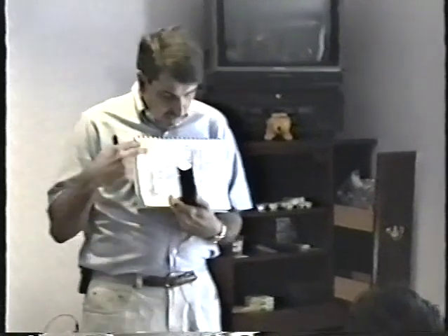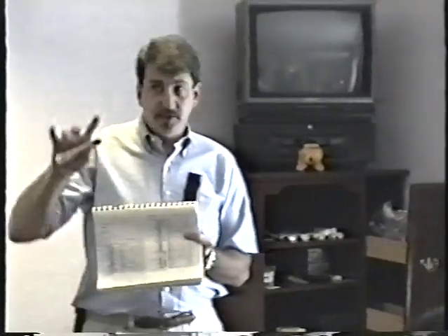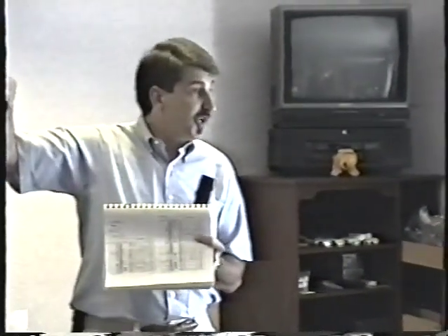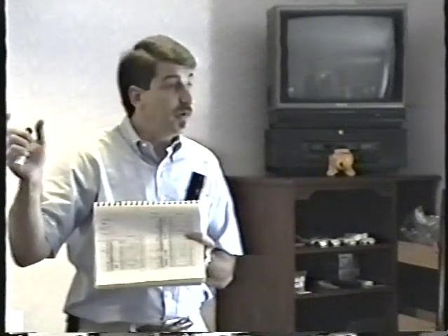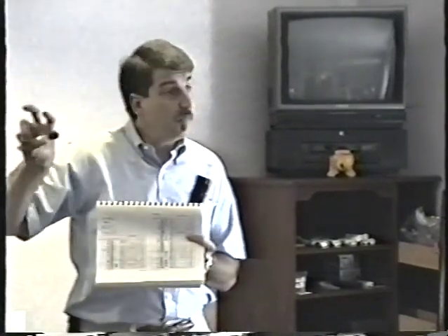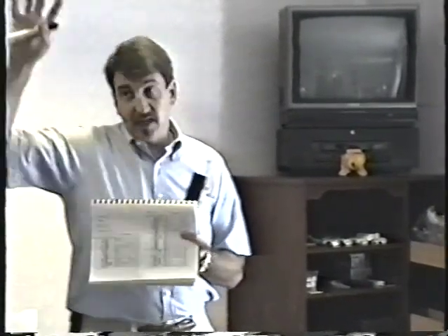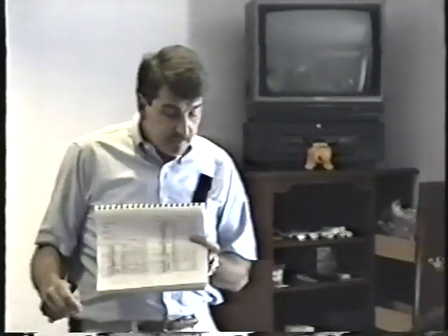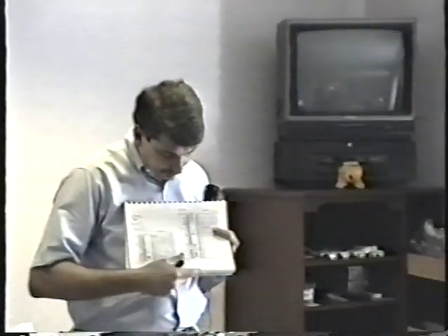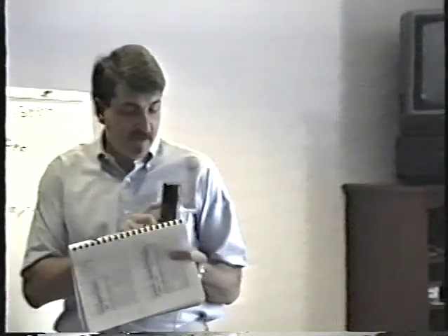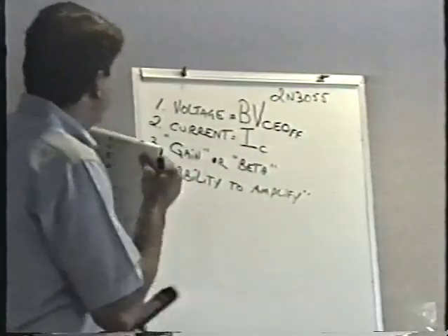All right? But we use complementary pairs occasionally. For instance, in a jukebox amplifier, there's usually two output transistors for each channel, left and right. Those are almost always complementary pairs. One's NPN, one's PNP. It's what they commonly call a push-pull circuit. You don't really have to know that either. But two transistors, same specs, opposite polarity. They're not interchangeable.